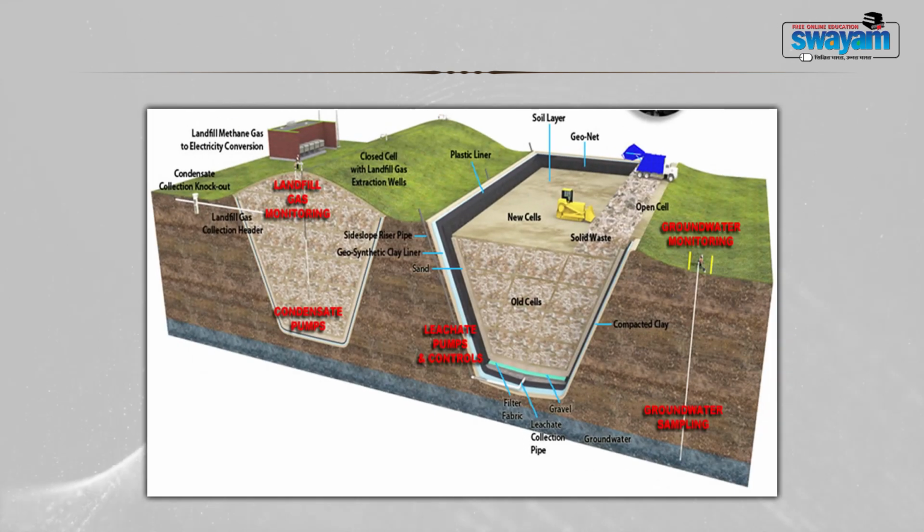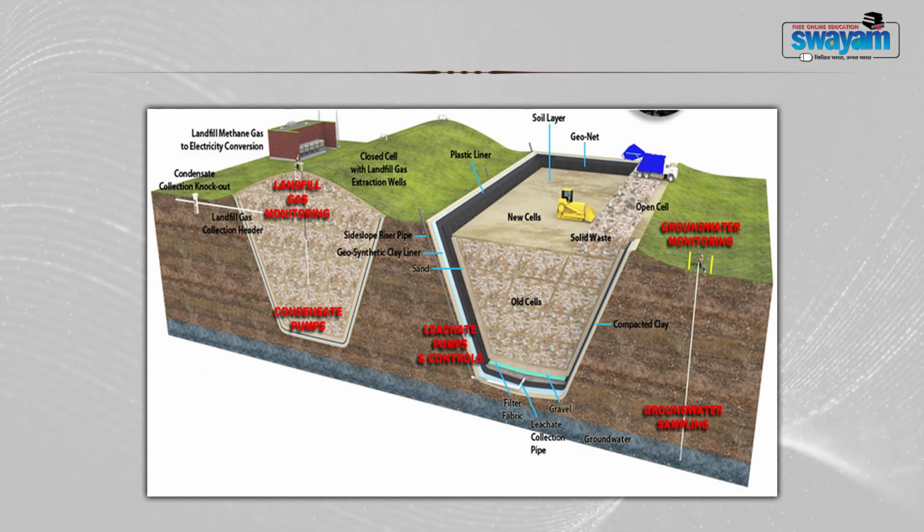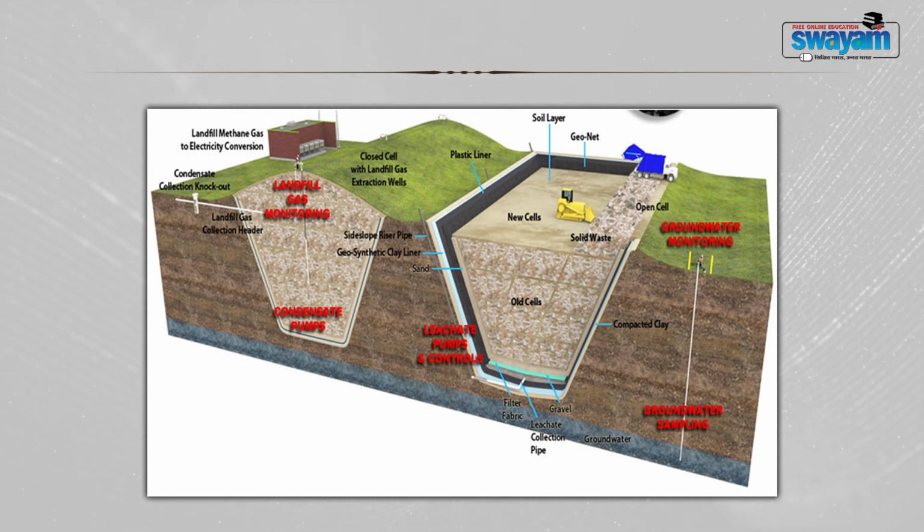Now, in this figure, you have an image of a landfill, or how a landfill actually looks. You can see how the land is trenched out, and then liner systems are laid at the bottom, and you can see leachate collection pumps which are set, and the waste is loaded in a systematic manner in the form of cells. You can see old cells at the bottom and new cells coming up at the top. Here you can see the truck disposing of the waste in a cell method.